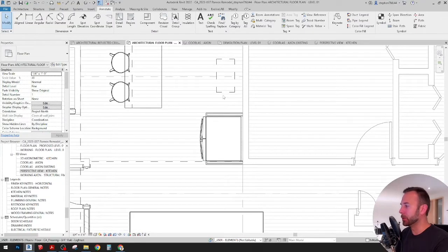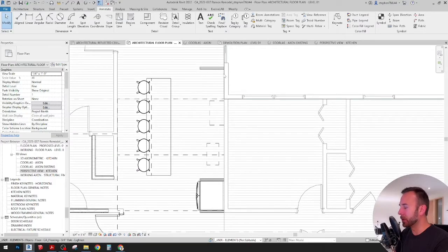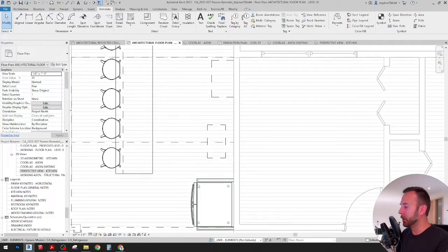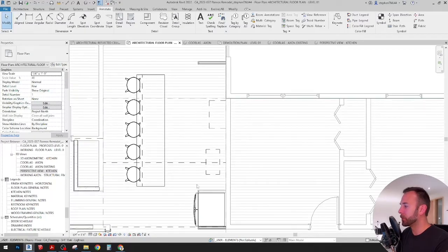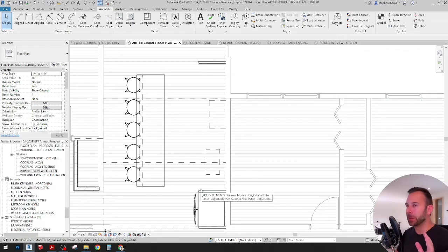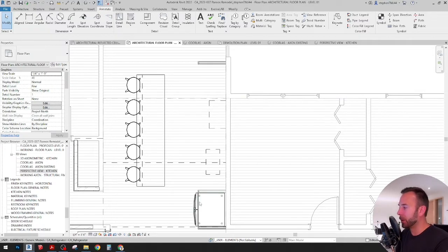That's why we like to do that little trick of setting the cabinetry out 6 inches, putting a ledger board on the back wall to support the countertop, and then you'll see at the end of this you get basically a flush cabinetry system with your refrigerator without having that odd or awkward refrigerator protruding forward in front of your primary cabinets.